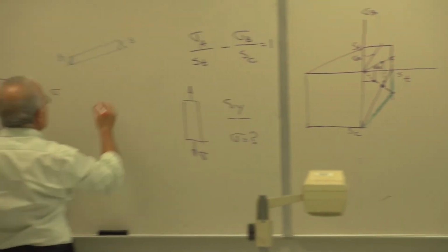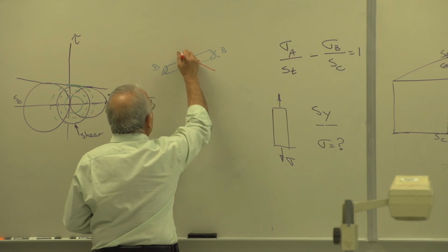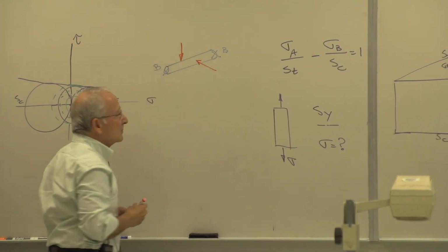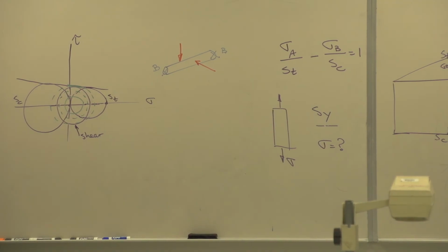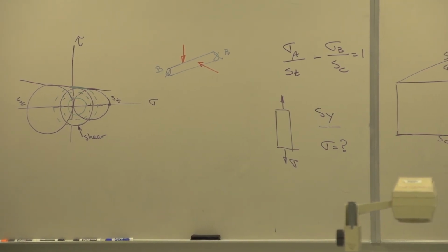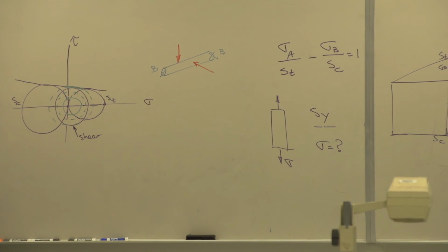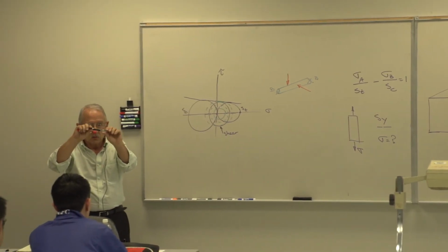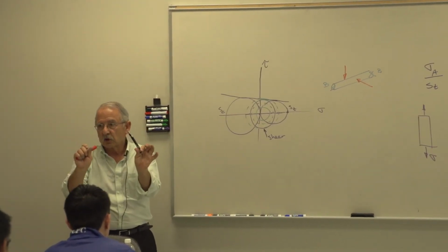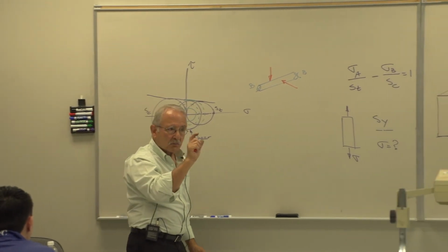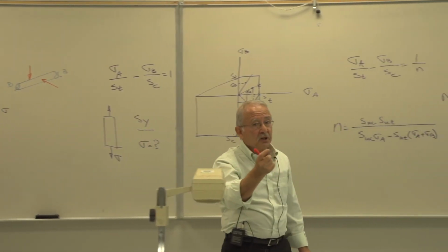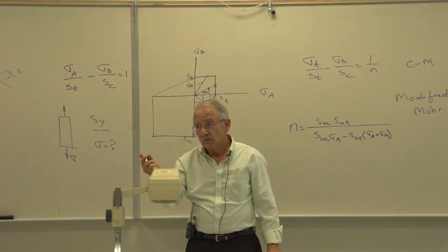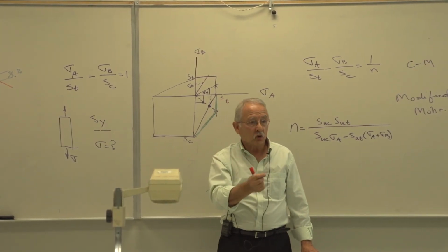And you have forces like that in two different directions. So one of them gives you a bending moment, for example, in this direction, in the horizontal plane. The other one gives you a bending moment in the vertical plane. The maximum moment is the sum of those two. And by sum, I don't mean adding their magnitudes, but adding them vectorially.